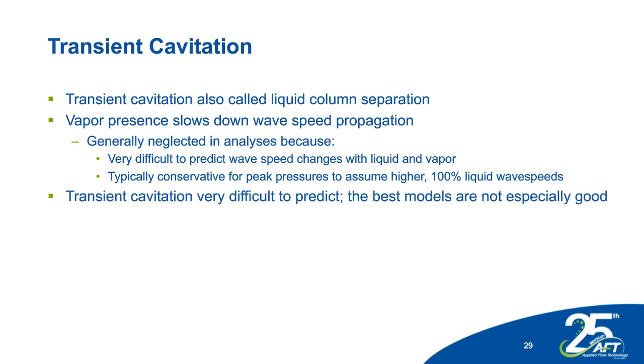It is difficult to predict transient cavitation because in reality, your wave speed is changing, but with various cavitation models, they're not going to always capture how your wave speed is actually changing. So this is where the models can start to differ from reality.